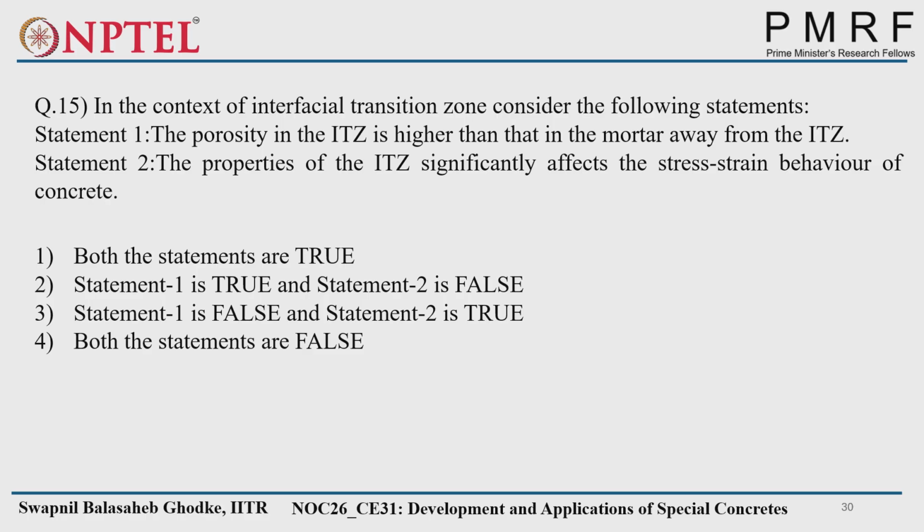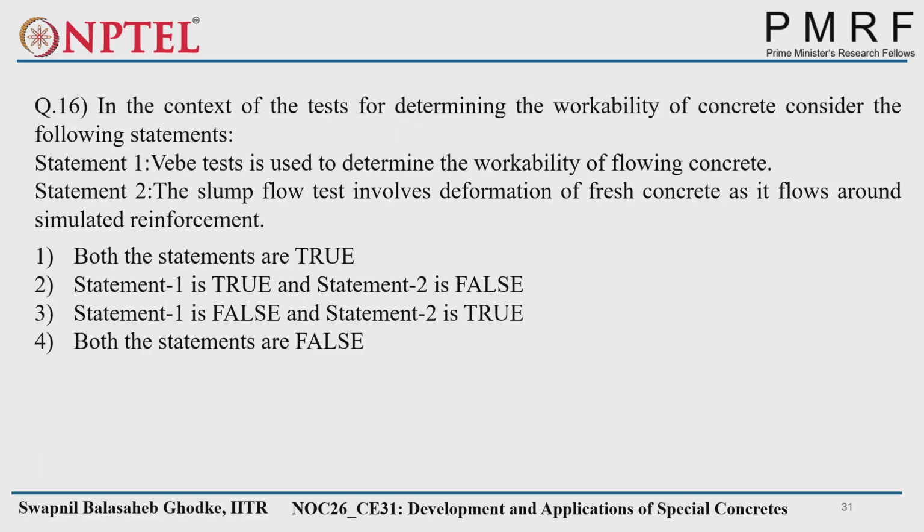The porosity in the ITZ is higher, right? Because of the higher water to cement ratio. The first is correct. The properties of the ITZ significantly affect the stress strain behavior. We already saw why it affects: because it affects strength, stress strain, and other durability properties also. So both the statements are true.